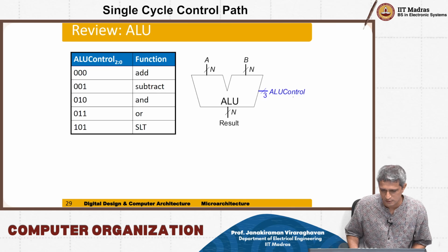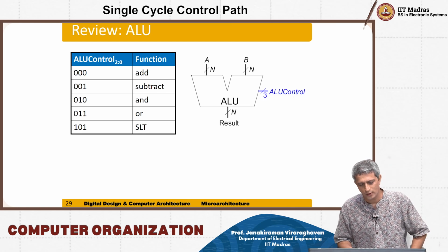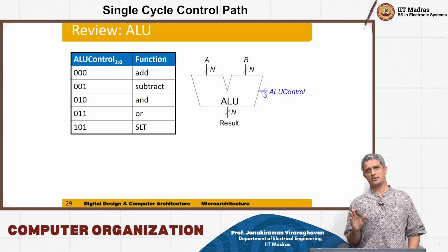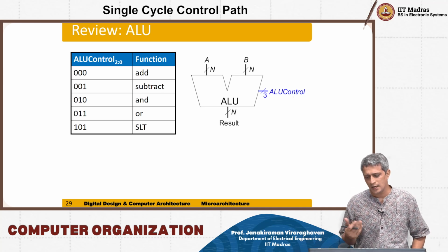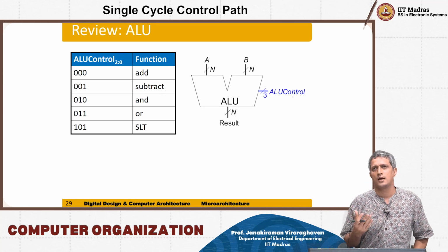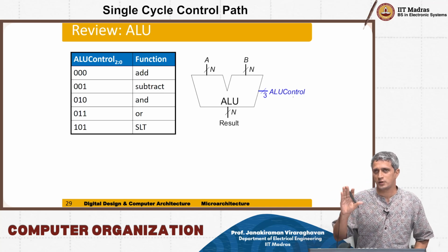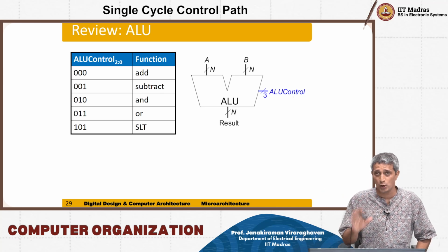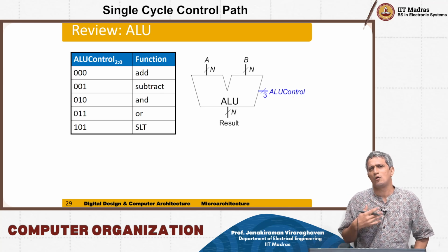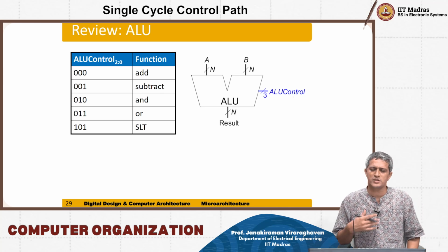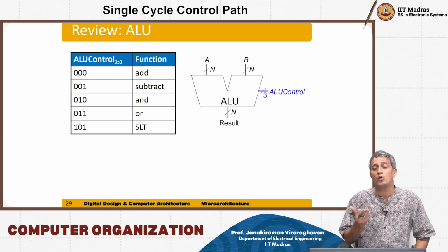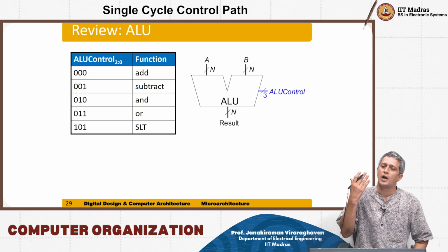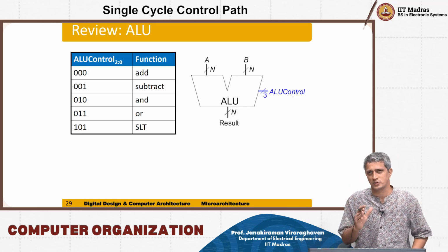If you look at this, the RISC ALU does not allow all sorts of operations, intentionally. In RISC-V, apart from the load store type of architecture where you isolate memory from ALU operations, which is a very good thing, you also don't allow all sorts of arithmetic operations. It becomes easier to implement, and more importantly, much easier to test such a processor when you want to design and fabricate it in reality.